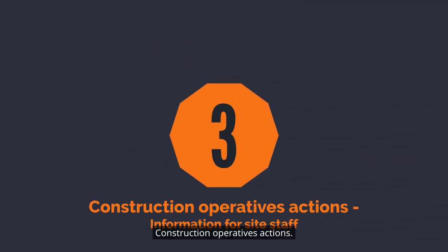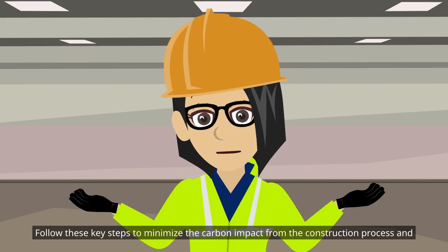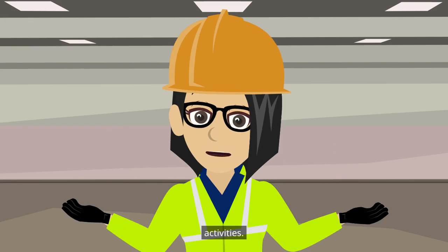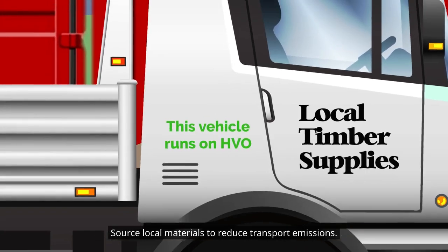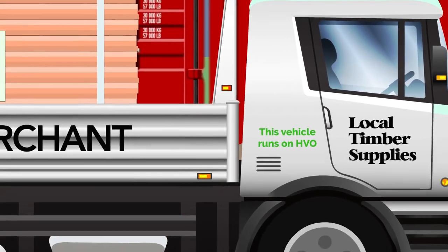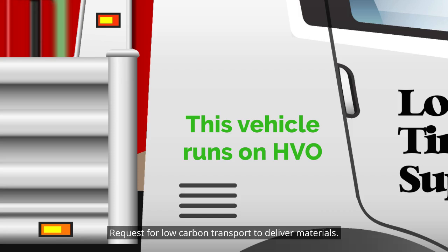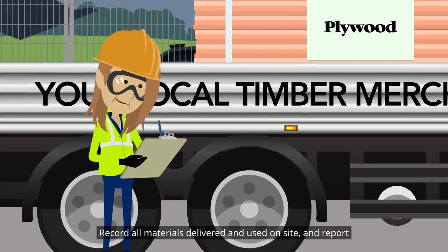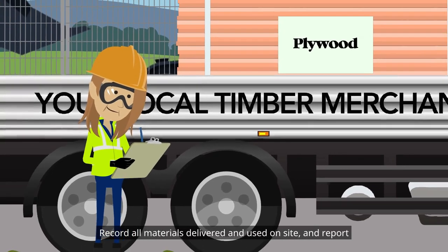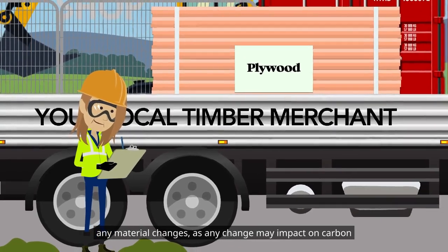Construction operatives' actions. Information for site staff. Follow these key steps to minimize the carbon impact from the construction process and activities. Source local materials to reduce transport emissions. Request low-carbon transport to deliver materials. Record all materials delivered and used on site, and report any material changes, as any change may impact on carbon emissions.